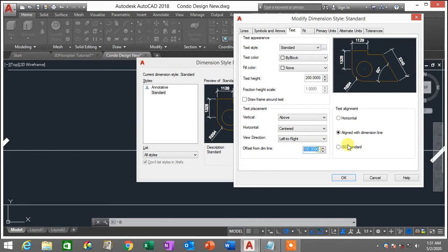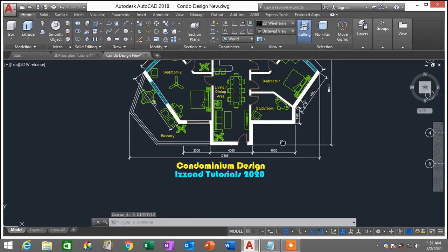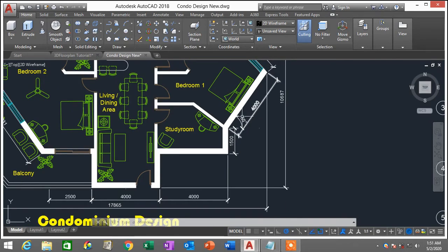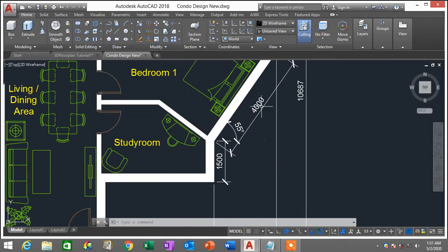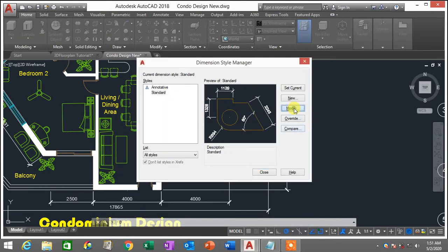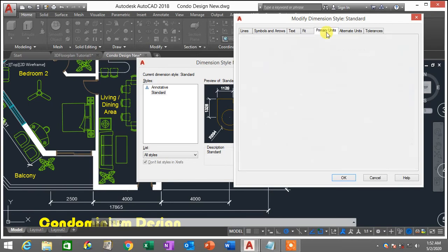So you may also choose a line with dimension line, so that when the dimension goes slanted, when it actually calculates, the dimension actually tries to calculate a slanted object, the dimension itself is going to be parallel to the object, right, or aligned with the object, like for this case, right? So it's better for us to use a line with dimension line, just to make sure that this dimension is aligned with the object, if the object is oriented slanted like this.